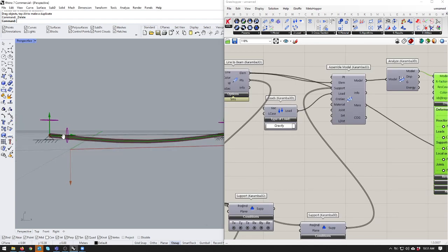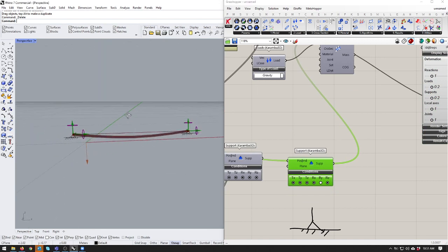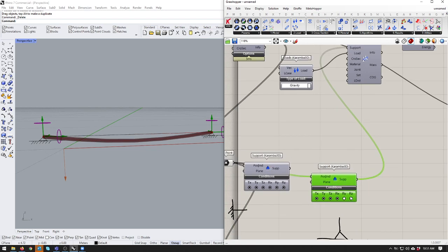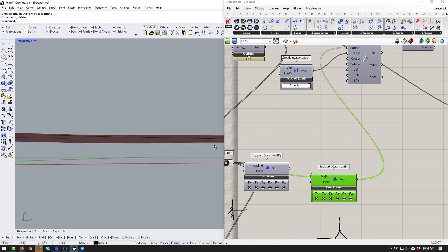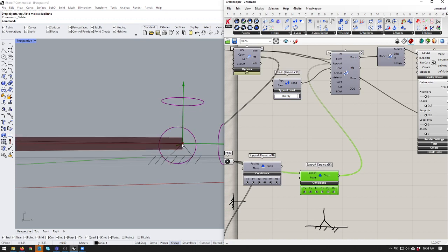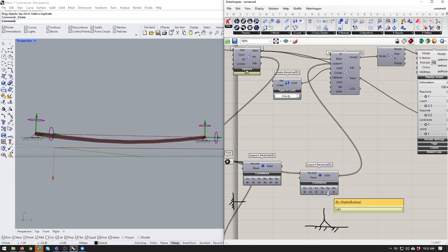And look, right now we're looking at two pin joints. We can see very quickly what happens if we make these pin joints rigid supports by just changing that rotational factor here. So this isn't allowed to rotate, and by making these rigid supports on either end, we're seeing a much better deformation result because of that support running through. Do you guys kind of see the benefits of being able to just quickly play with that?